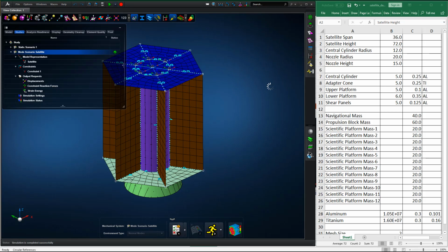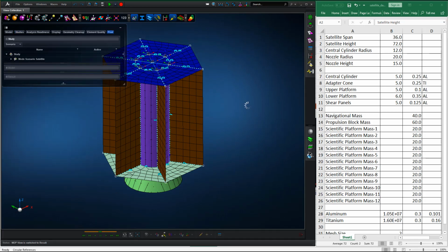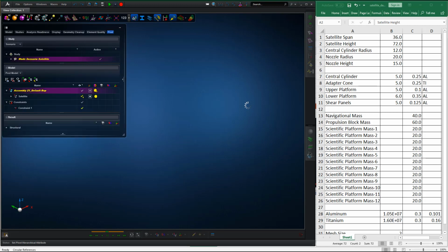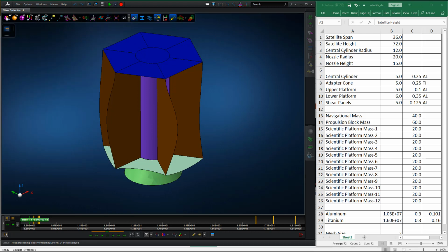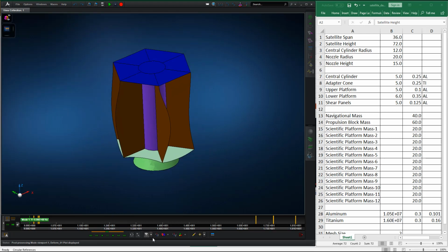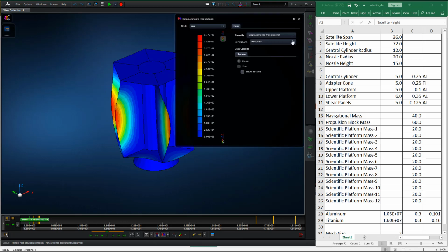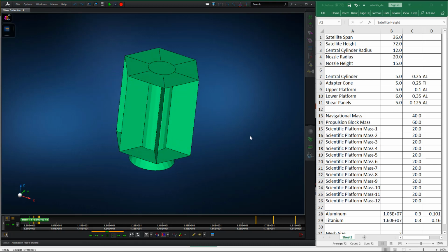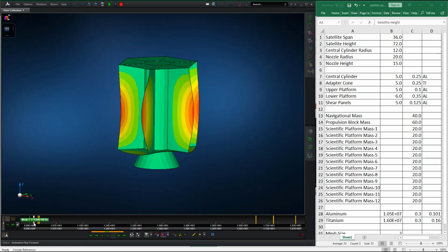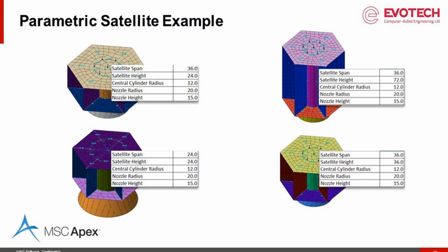So you've got full model control, perhaps a little bit more powerful when used in the appropriate manner over things like topology optimization and size and shape, but we can see how those changes are washed through in terms of the analysis very quickly. So just looking at some of the mode shapes for the normal modes analysis, we can see fringe plot, animation of deformation, showing what that particular type of structure would do. So again, just a quick slide to illustrate, by changing some of the key parameters we can look at four very different geometry sets and understand their behaviour in terms of the overall structure.